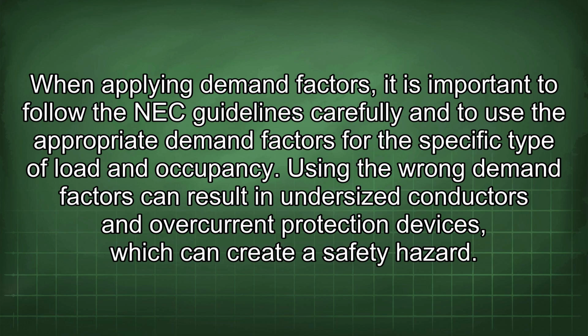When applying demand factors, it is important to follow the NEC guidelines carefully and to use the appropriate demand factors for the specific type of load and occupancy. Using the wrong demand factors can result in undersized conductors and overcurrent protection devices, which can create a safety hazard.